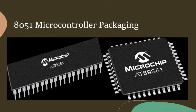8051 microcontroller is available in a variety of IC packaging types. The most popular and commonly used 8051 microcontroller package is dual inline, or DIP. It is often available as a 40-pin dual inline package or plastic dual inline package IC. The other common packaging type is 44 lead plastic leaded chip carrier. It is a kind of surface mount package. Another surface mount package for 8051 microcontroller is 44 lead thin quad flat package.